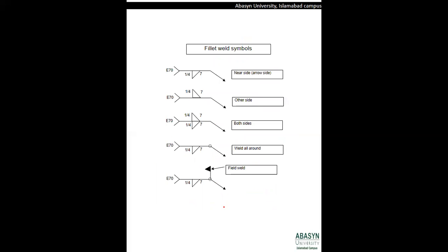Well, in the drawings of steel structures, how would we know how to represent the welded connections? There are many terminologies that we use to represent such symbols. For example, if we have electrode E70, it is mentioned at the start of the symbol, at the tail of the arrow. Whether we use an E60, E70 or E80 electrode, the electrode is mentioned first,